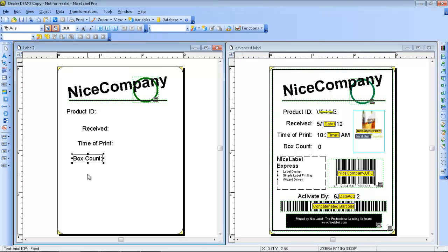Okay, now if you hold down your left mouse button and scroll over all these fields, it will highlight them. Now I can go to my left toolbar, click on the left justification, and scroll down a little bit further for vertically spaced equally. So now you can see they're lined up perfectly now.